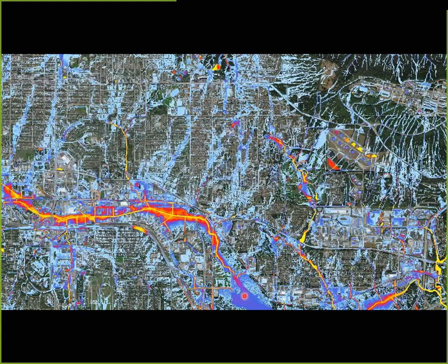Now, development that's happened within the city, generally it tries to get rid of these overland flow paths because that's land that would otherwise not be developed if you left it green for creeks. So development approaches over time have obviously changed. New developments in an area like this would be required to retain these water courses and so on. But in the past, that is something that was not done. So these risks from overland flows across the community do exist, particularly in older areas, and the impacts of this sort of rainfall can be quite extensive.